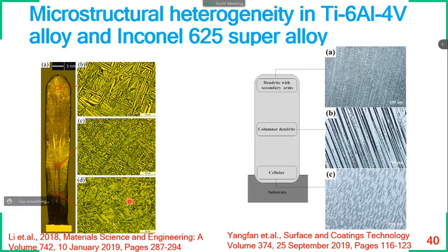And if you ask, is it everywhere we will get the same microstructure in WAAM? It is not possible. WAAM is known for microstructural heterogeneity. Heterogeneity means everywhere you can notice different grain size and different grain orientation. In a single wall component, this is the cross-sectional morphology: the top layer was featured with very coarse grains, the middle layer with intermediate grains, and the bottommost layer with fine recrystallized grains.